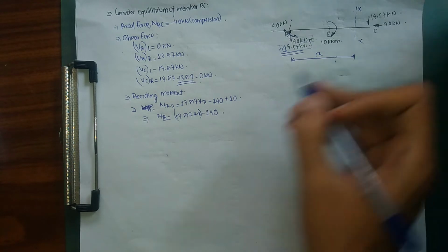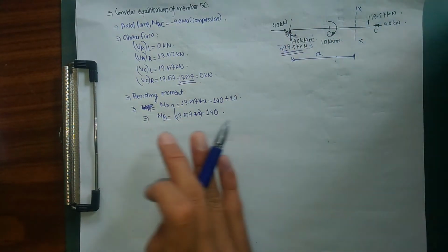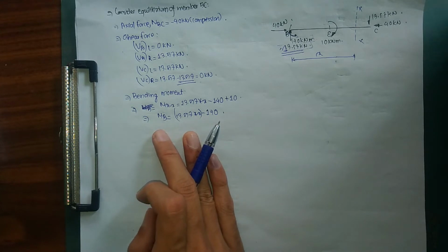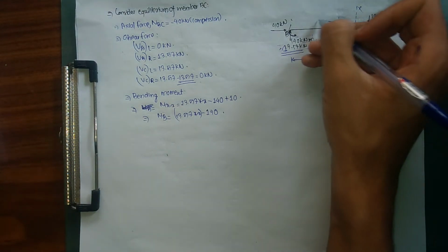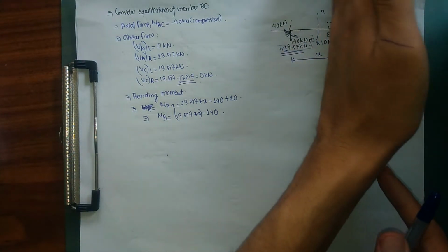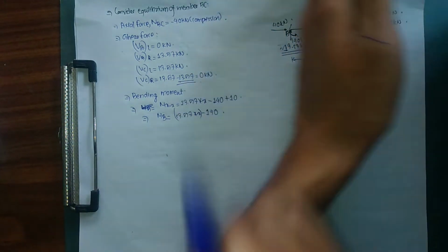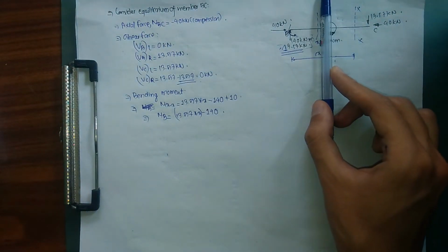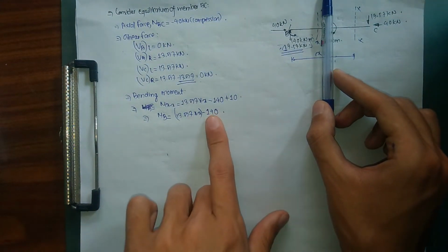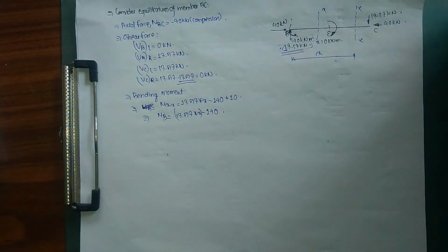This is going to be our bending moment for our overall beam, but in order to find our bending moment for our portion B, we have to take our section over here, because we do not need to include our 10 kN per meter. So we need to see the section over here only. The 10 kN per meter is not going to be included, so we are going to exclude that, and we are going to put on this only.